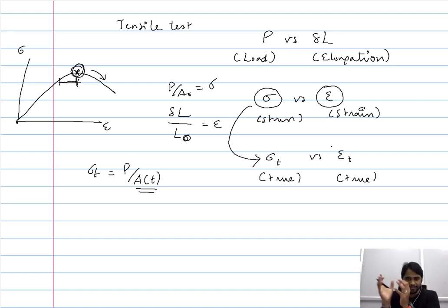So when you talk about the tensile test from the practical point of view, even though there are different ways of representing the outcomes of the tensile test, the most preliminary way of using load and deformation, the other way of using engineering stress and engineering strain, and the final way, or the most accurate way, of true stress and true strain, we generally use engineering stress and engineering strain because, one, when compared to the load and deformation, it is independent of the initial dimension.